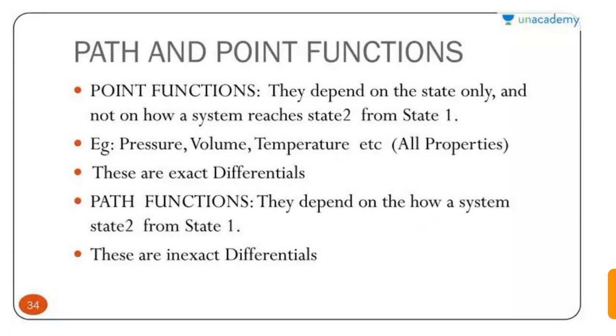Now what are path and point functions? Point functions depend on the state only and not on how a system reaches state 2 from state 1. They only depend on the state. These are point functions. Examples: pressure, volume, temperature. These properties are all point functions, and they are exact differentials. Point functions are exact differentials, but path functions are not exact differentials.